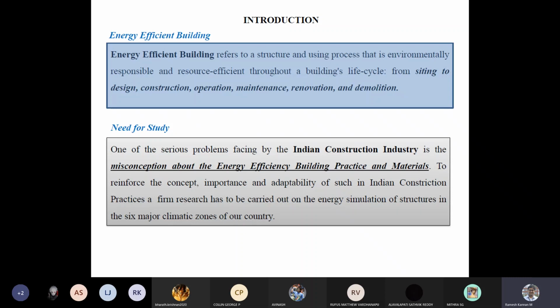Generally, people take a particular truss that can hold the maximum load for the given span. But now people look into the material aspects, like what material is used and its strength-to-weight ratio, right? They take all those things into consideration, and they also look into the economic aspect, like whether it is costlier. Everything they consider. Say, for example, if they are able to save at least 2 tons of steel used in the entire project, then that will be a safer, more sustainable construction, right?